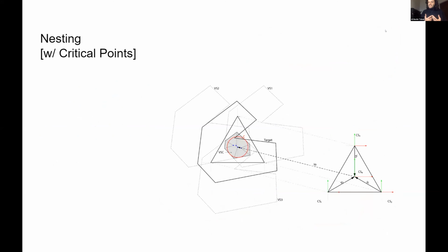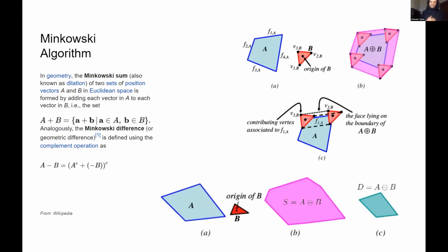So what we did is we used the same strategy that we designed for gripping. We had this algorithm that the robot can automatically calculate some kind of gripping strategy to pick the piece up. And this algorithm includes using some points and defining some specific points. And then we have this customized nesting algorithm that finds a way to fit all those points into some polygon that we defined. In this case, we defined the polygon as the material piece that we have. And we also defined some critical points on the panels that we have designed, and we use the same algorithm to fit them together. However, points are not enough for defining the critical portions of the panels that we have designed.